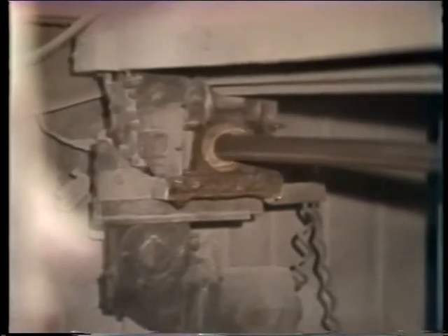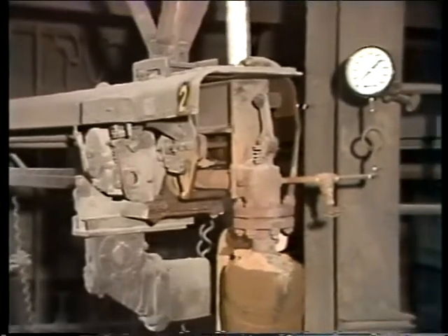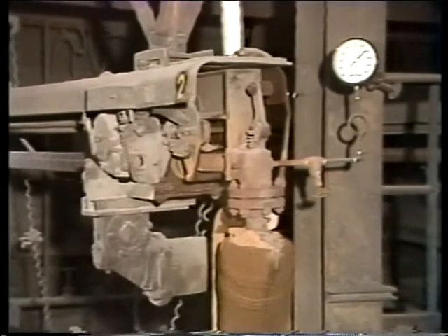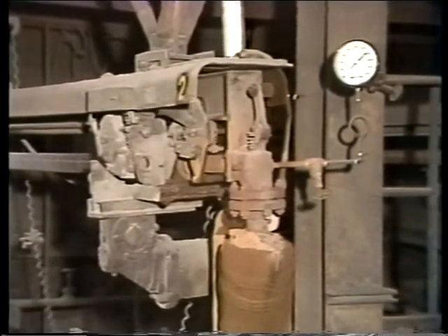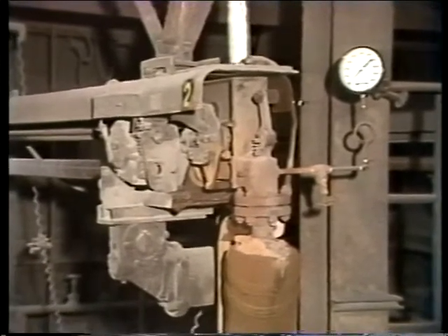Ordinarily, the traveling drive will trip a limit switch at the end of its outward travel, and the element will be geared to turn a quarter turn before the carriage and element begin to withdraw from the boiler. As the element is retracted, the carriage trips the valve trigger shut near the end of its travel. When the outer limit switch is tripped, the blower cycle is complete.